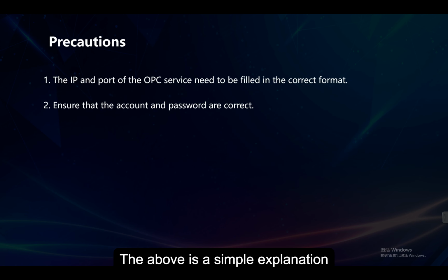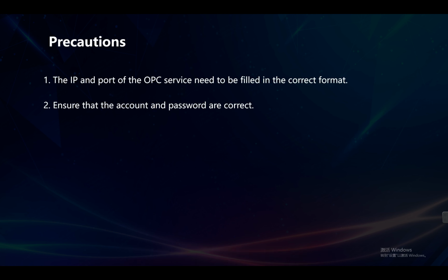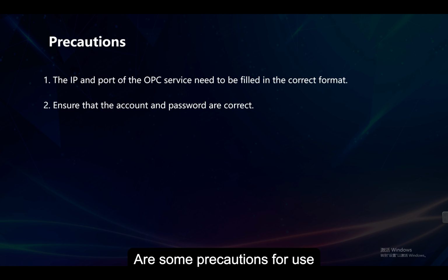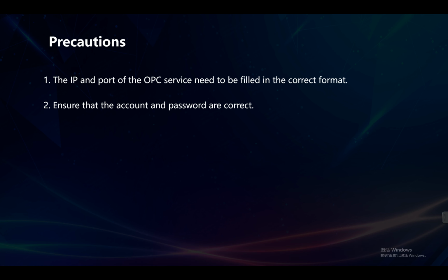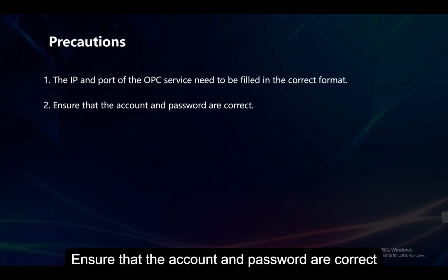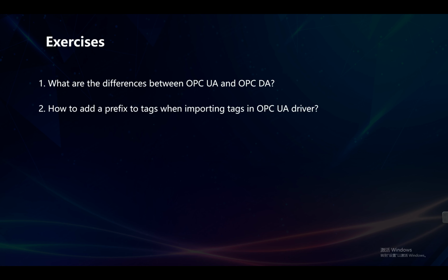The above is a simple explanation. Here are some precautions for use. The IP and port of the OPC service need to be filled in the correct format. The second point is, ensure that the account and password are correct.